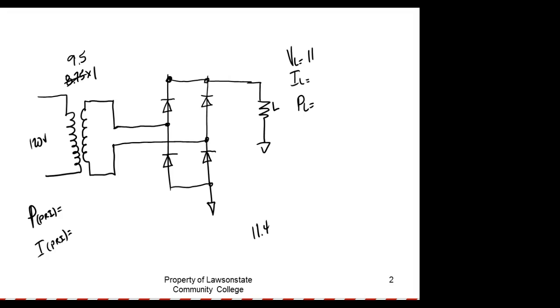Hmm. If you go the long way, it comes up to be 10.5 volts. Still not bad, is it? Something's going on here. Oh, I know what's going on. I was using the center tap instead of the outside.